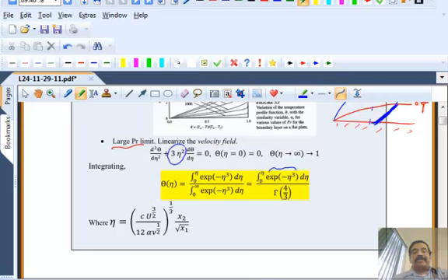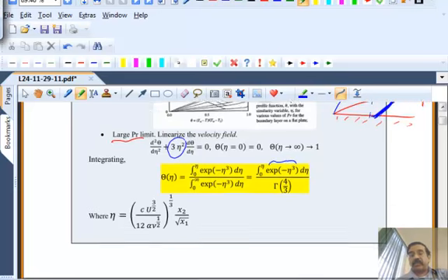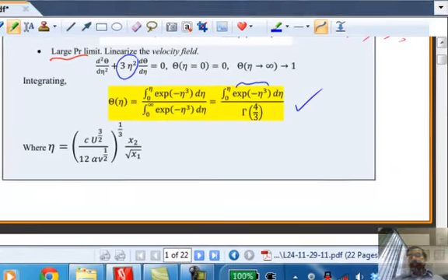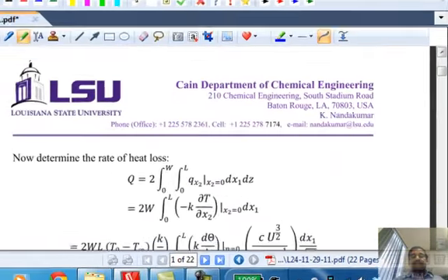What we need to do now is take these expressions. Remember, always when you're solving the momentum equation, you get the velocity profile, but what you are really interested in is the forces, the drag force, for example, the lift force. In a similar way, when you're solving a heat transfer equation, you get the temperature profile as you did here. What you're really interested in is the heat flux or the Nusselt number. Okay? And in mass transfer, the same thing. You follow the same ideas, you get the concentration profile, but you're interested in the mass flux, how much material is entering the domain through the boundary.